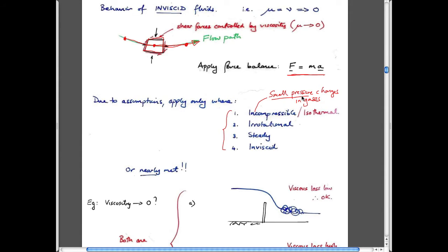Irrotational just means that there are no eddies in the system. And so when we have circulations downstream of weirs, for instance, where you have circulation occurring in eddies, both in vertical plane or in circulatory in plan view, as you look at a river, then that's not applicable for us, so we don't have to worry too much. The most important ones, because they occur, are that the fluid pressure changes shouldn't be large. Don't worry about these because we won't have to deal with those so much.